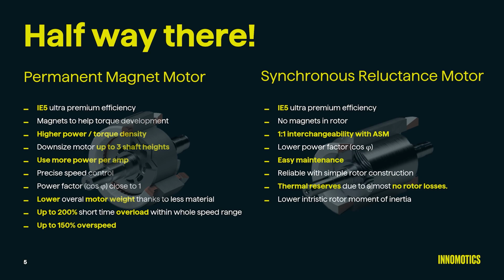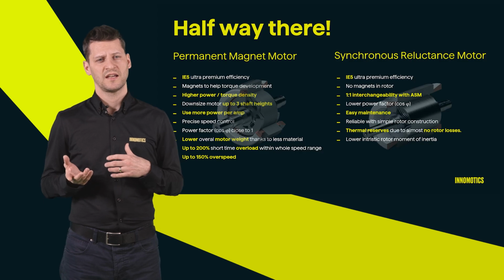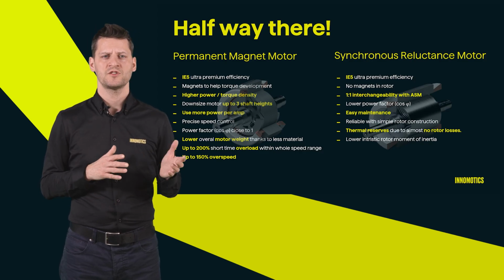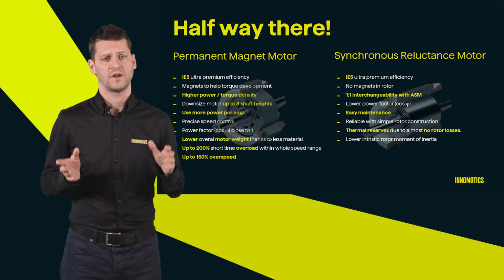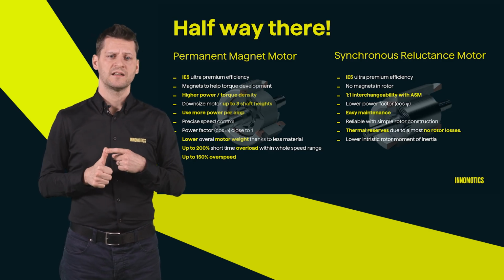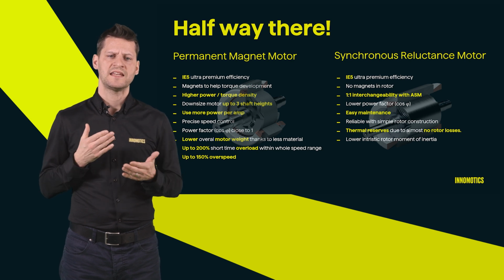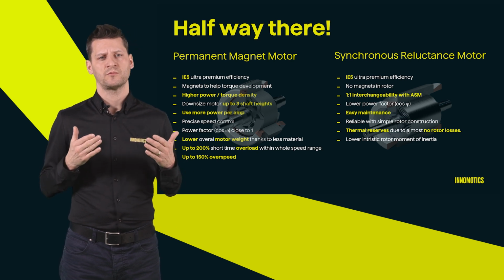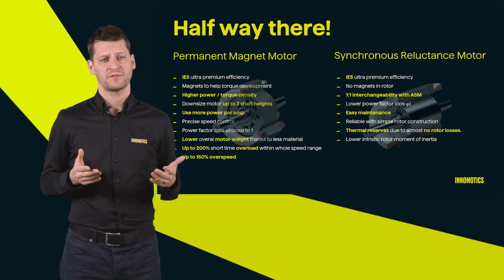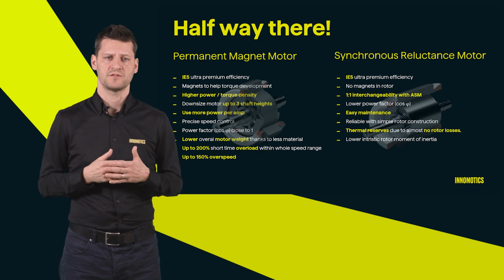If we have a look at the synchronous reluctance motors, there's the advantage of mechanical compatibility and one-to-one interchangeability with asynchronous motors. They are magnets-free, they are very reliable, easy maintenance, and they have really low intrinsic moment of inertia, so it's a perfect fit for high dynamic applications.